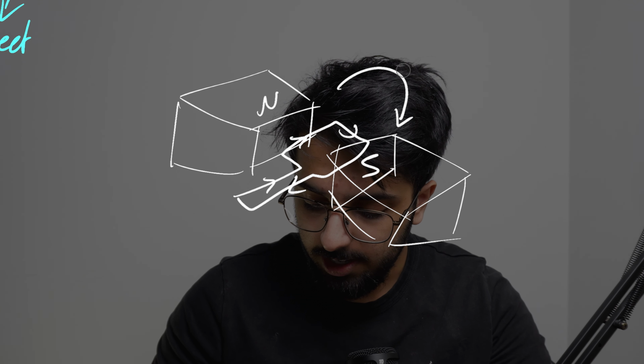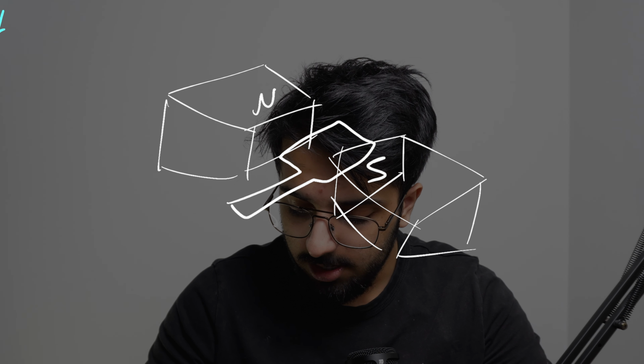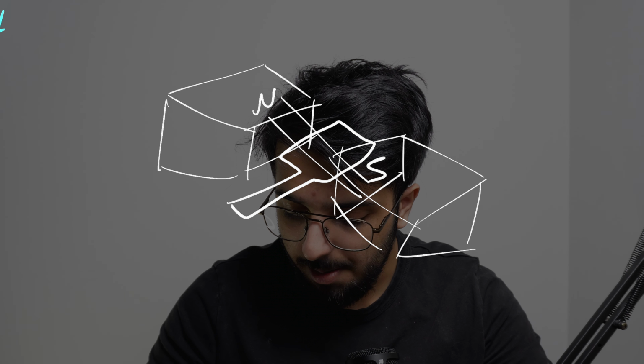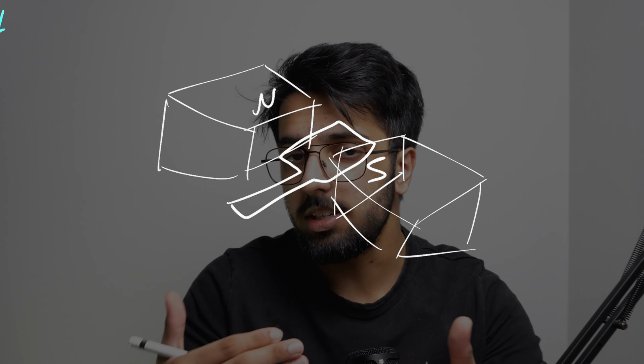A generator is the opposite situation. In a generator, we would rotate the coil, and then as the coil interferes with the magnetic field generated by these permanent magnets, a current will be induced in that coil. So you see how a generator is just the opposite of a motor. In a motor, we put a current through the coil, and that causes the coil to rotate. But in a generator, we rotate the coil, and that induces a voltage and therefore produces a current within the coil, therefore converting mechanical energy into electrical energy.